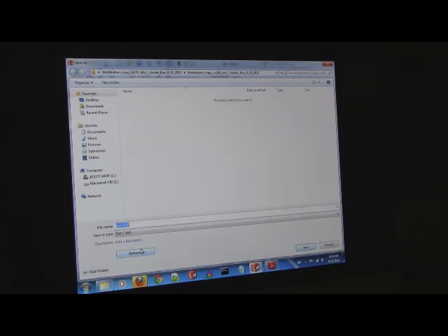So I don't expect most people to get this right in the first try because I don't know what the settings are. Basically, if I can't open your file, we're going to twiddle around with your laptop. So when you come to get your stuff laser cut, bring your laptop with SolidWorks and your mouse because we're probably going to be screwing around with the DXF file format until it works.